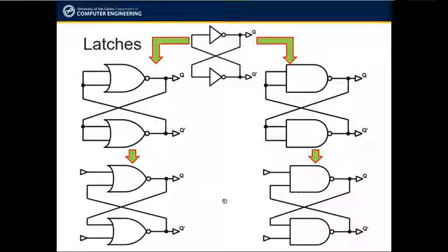You can now see that the two circuit implementations can now accept inputs. With that, we can already vary their outputs and influence their storage and memory characteristics. These two circuits are now the basic implementations of an SR latch. SR latch using NOR gates and SR latch using NAND gates.